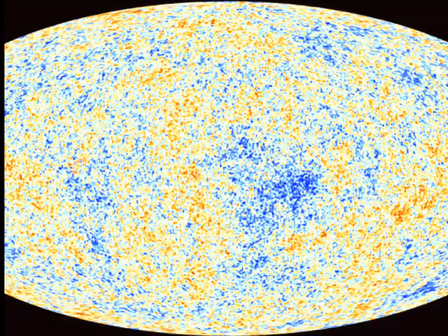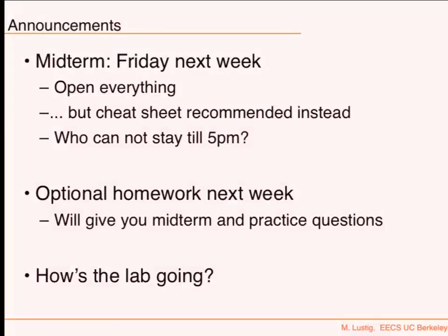So, FFT shift. All it does is take the last part of the DFT and shift it. There are no indexes, it's just vectors. There's no indexing there. It just takes the last part of the vector and puts it in the beginning. That would then correspond to negative frequencies and positive frequencies. Was there a question here?